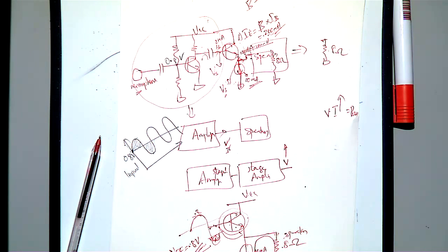But then when you connect this diode, this diode should be getting some power from somewhere. So that is the reason. What will you do? You have to connect this to the VCC. Then we will not short it directly, we will use a current source, because this current source will set the current, and this current will be sufficient for biasing this Q1 and then sufficient for flowing through these diodes and giving the bias. You know how it is evolving.